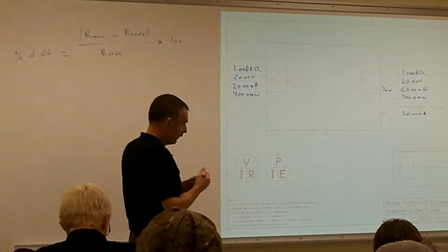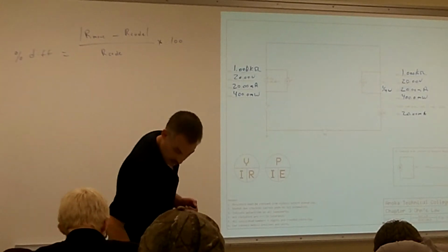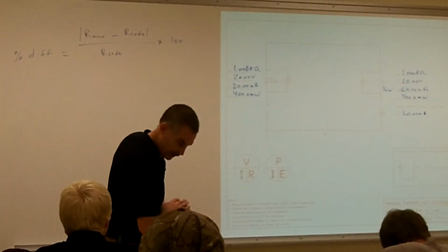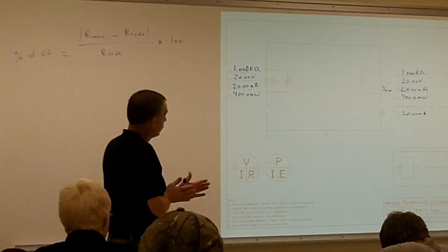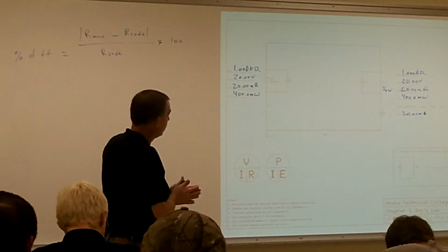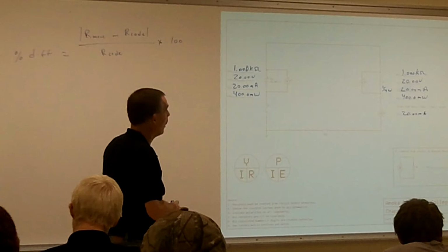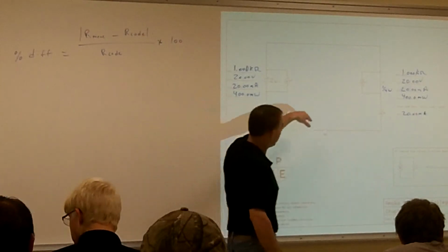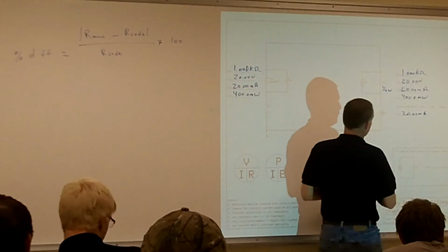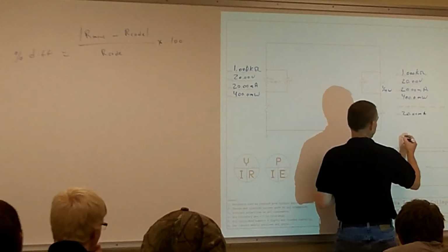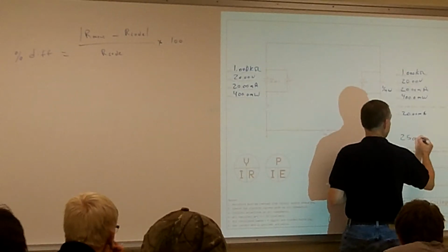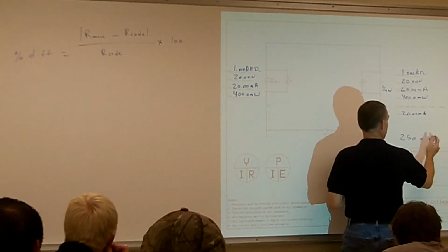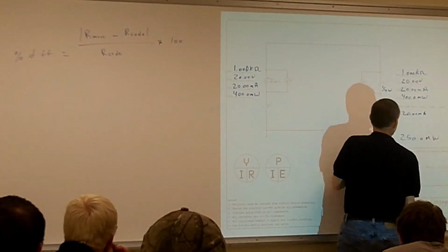That's the rating of that resistor. I'm looking over on page 91 where they have the ratings of the watt resistors. If it's 1/4 watt, would that resistor be okay to use in that circuit? No. Because 1/4 watt is actually equal to how many milliwatts? 250 milliwatts. So I have 150 extra milliwatts that's going to really heat up that resistor.